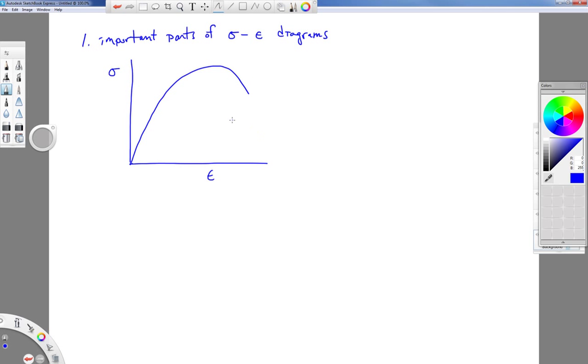All right, so here's a typical stress-strain sketch behavior. We start off with zero load, and we have zero change in length, so we're down here at this corner point. We increase the load, the stress increases, and the strain increases. And the initial portion of this, for a lot of materials, a lot of metals in particular, is a straight line. Then it starts to get into kind of this curvy portion that hits a peak, comes down from the peak a little bit, and it breaks.